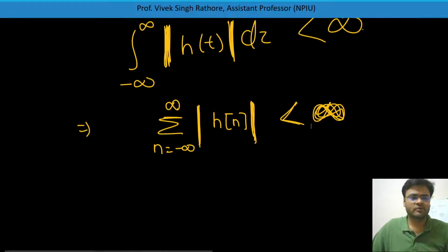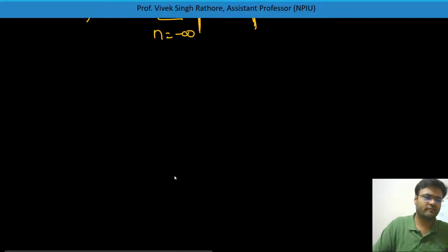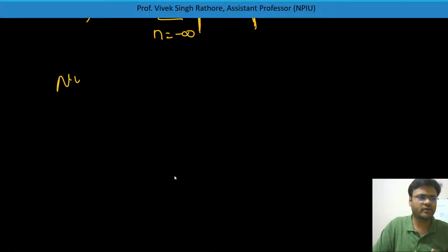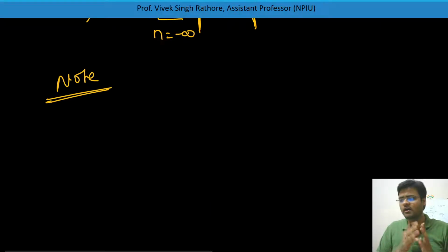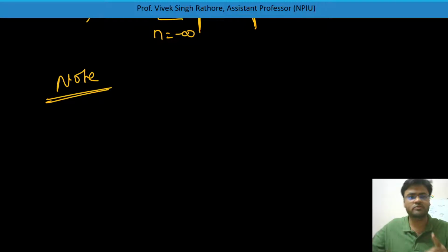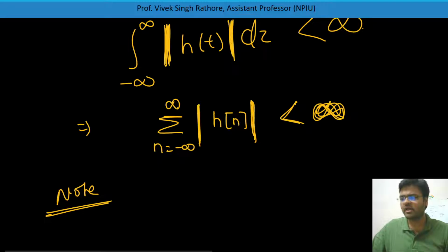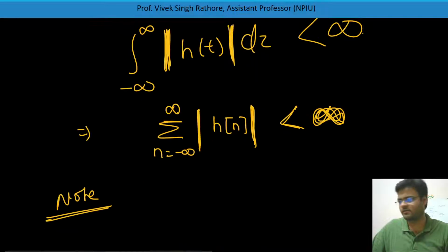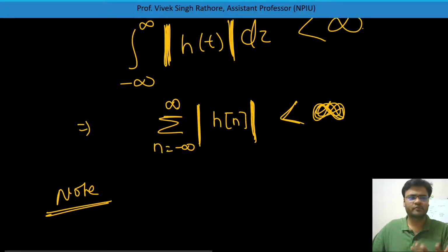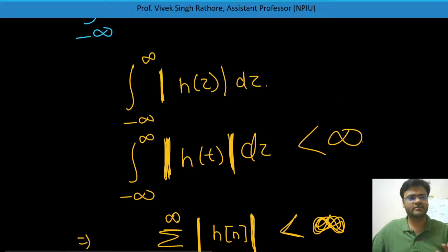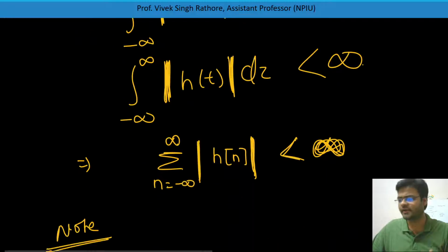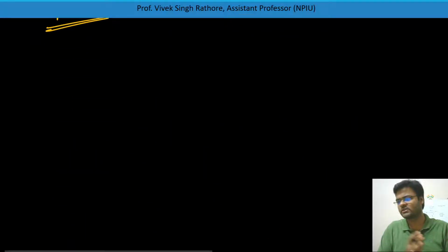So the final point I need to tell you is that a continuous time LTI system is stable only if its impulse response is absolutely integrable, or absolutely summable for discrete time. Only then is your system said to be a stable system.